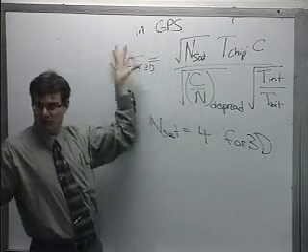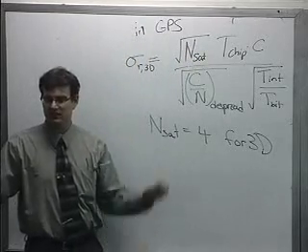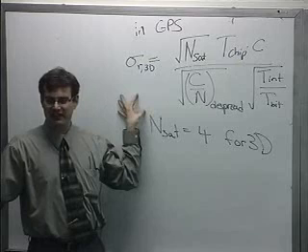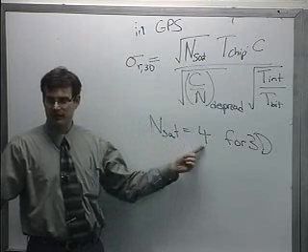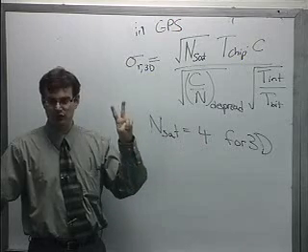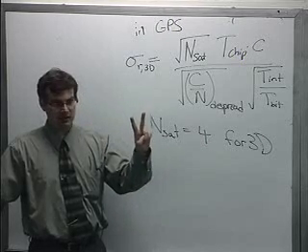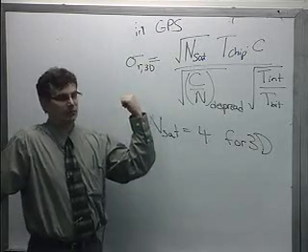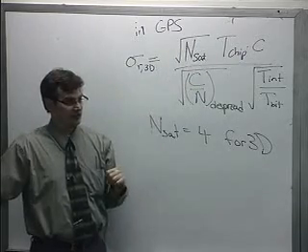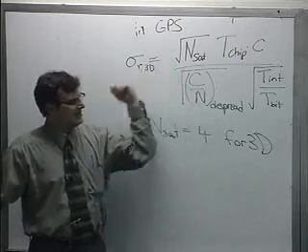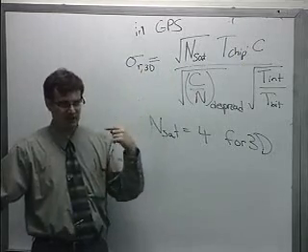And this is not the formula for that case. This is for the maximum number of satellites that you are required to use. So if you're doing a 3D estimate, you plug in 4. If you're doing a 2D estimate, you plug in 3, because you need time and then XY. If you're doing the 1D meaningless case that we were studying over there, you plug in 1.